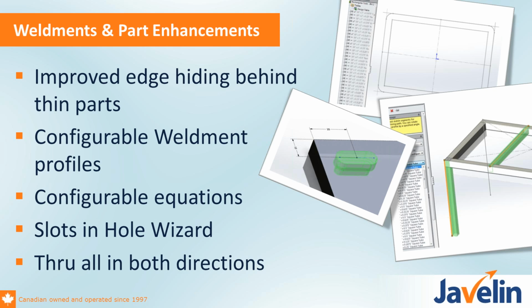Slots is a brand new area, and I love how it's an extension of Hole Wizard. You just use the same Hole Wizard you did before, but now instead of just a straight hole, you can drill a slot or machine a slot. There's a quick way to do through all in both directions as well, which is nice.